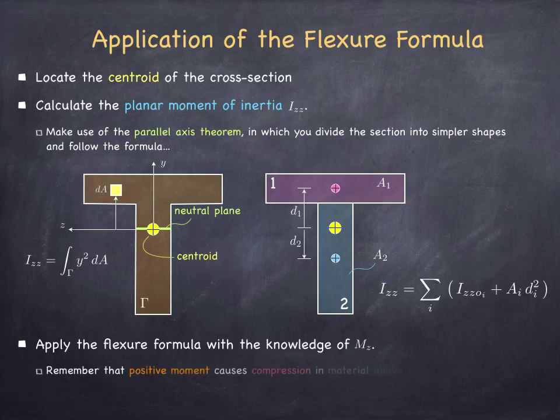And of course, in all these calculations, I better remember that the positive moment causes a compression in the material fibers above the neutral plane, and that it causes tension in the material below the neutral plane.